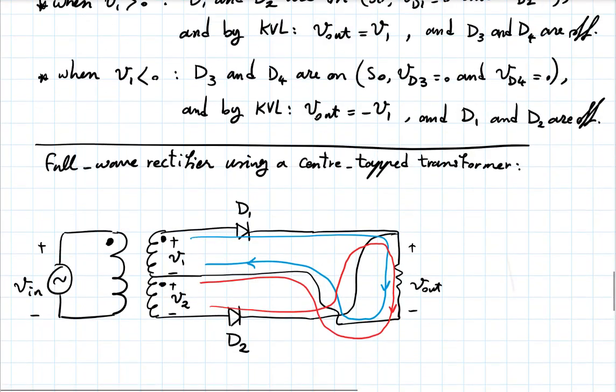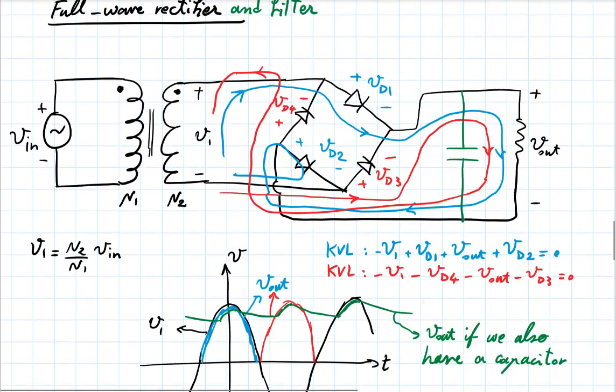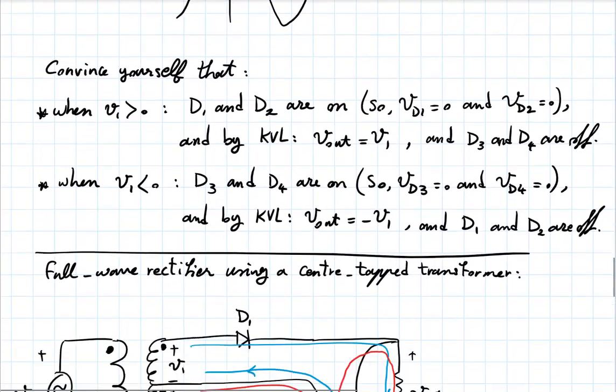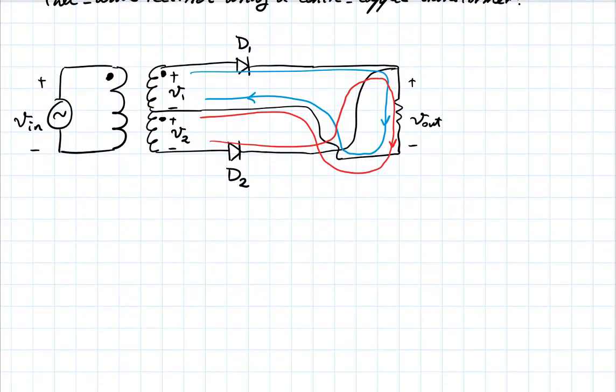But one thing you could say maybe is that, you see here, what if the diodes were not ideal? If each of them wanted an approximately 0.7 volt drop? Well, the output would be 1.4 volts below the input, right? I would lose a total of 1.4 volts because I have 2 diodes worth of drops from the input to the output. Whereas in the other one, I'd have only 0.7 because I have 1 diode.